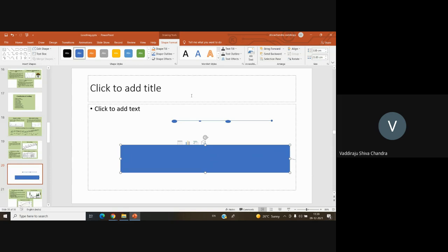Okay, so I'll be establishing my instrument at some position, from here or here, in any direction from where I am able to cover most of the area. After I establish my instrument, I will do the temporary adjustments: setting up of the instrument, leveling up, and focusing of the eyepiece and objective. And I'll take a benchmark. Okay, I'll take a reading on the benchmark, which is going to be my backside.